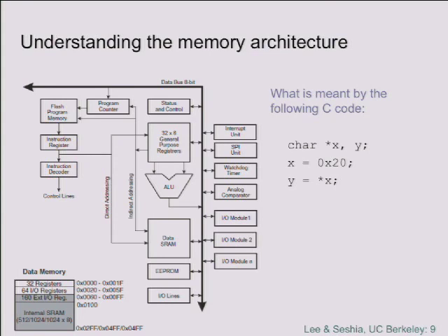So, all right, what does this code mean here? Yeah. You're reading the value? I mean, you set up X the same way, pointing towards the first. Right. So this is going to store into Y the value read from the first of these 64 I/O registers. That, by the way, might be telling you something about what the physical world is doing. You might have an external device that is controlling the value of that register, and you're reading it now, and now you've got it in your program. You know what the physical world is doing. You can do a branch on that. How much memory have I used up with this code?